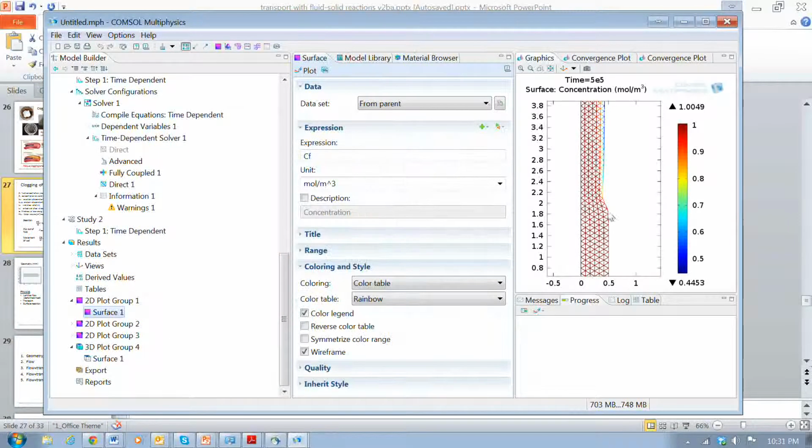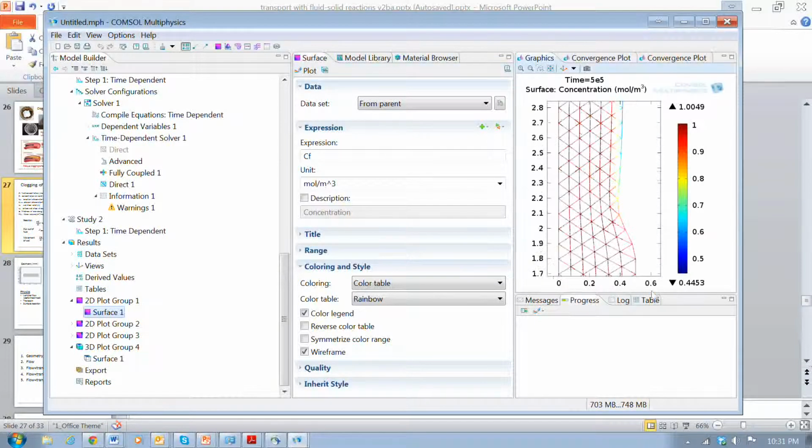But if you let this go further and this bulges in more and more, then the mesh will become increasingly deformed, and there may end up being numerical problems. What you can do is stop the run, and remake the mesh with this deformed geometry, and then continue it again. So that's always an option. So experiment around with this and try out various numerical experiments.